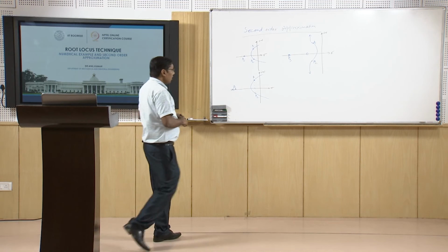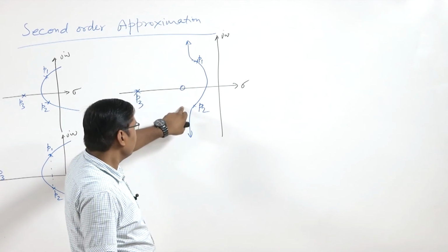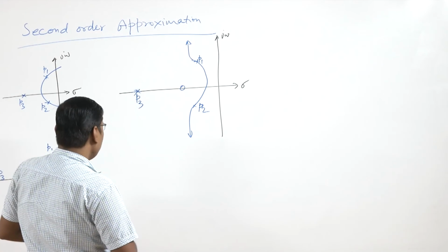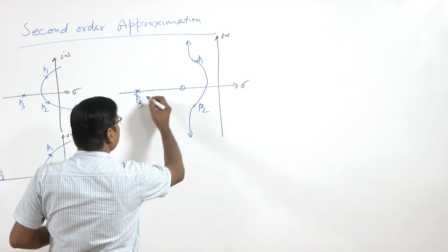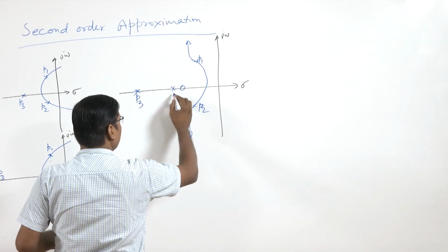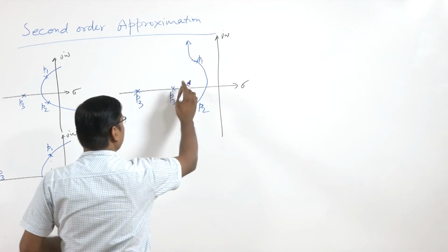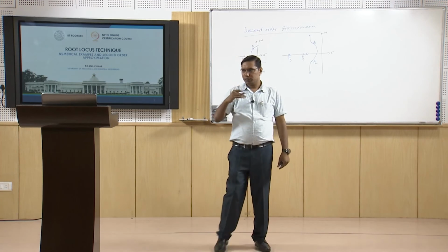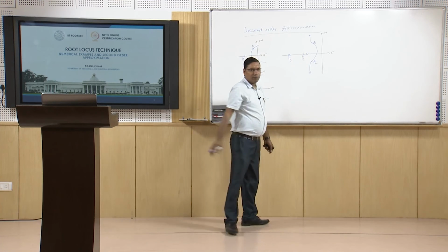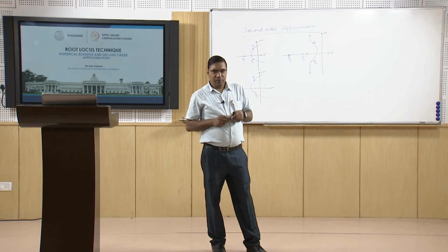So, if we have a 0 here, it will affect the response of this system, and the role of this 0 can be cancelled only if this third higher pole is near to the 0. Because we know that 0 is in the numerator and pole is in the denominator, due to close proximity of these two, this 0 and pole will be cancelled.